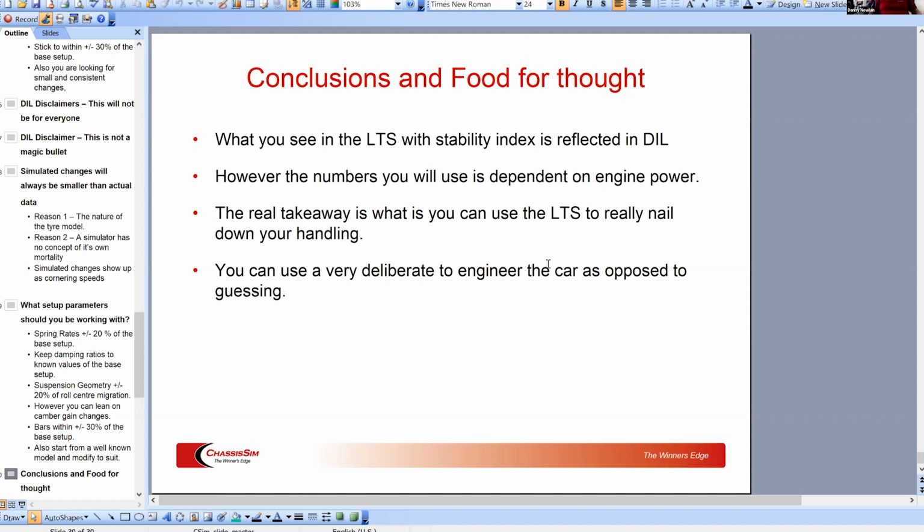So, if you're trying to ask the tire to do both ridiculous amounts of traction and cornering at the same time, it's not going to work, which is why with those values of the stability index, you actually shifted them backwards with increasing level of engine power, because the tire actually needed to have excess grip so that when the driver gets on the happy pedal, the car doesn't swap ends. It's a fundamental limitation of the tire.